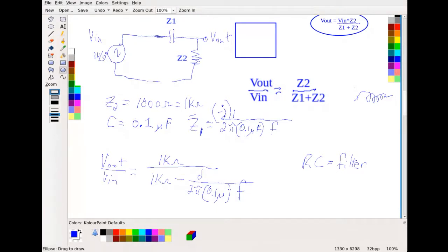But when you throw in an inductor, it could easily make that filter a $10 filter or something like that. $10 may not be much, but if you're going to build 1,000 of these, instead of $1,000 you're at $10,000. So if you can get away with just an RC filter as opposed to an RLC filter, adding an inductor, you're going to save a lot of money.